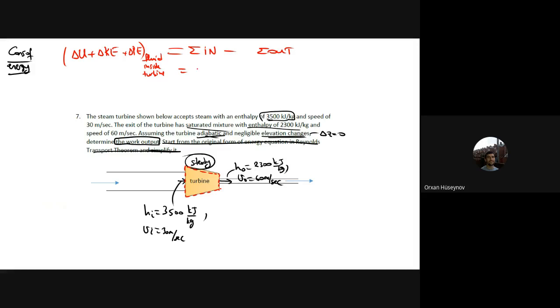And for the in quantities, you have the mass flow rate, so mass multiplied with the internal energy plus the P by rho plus the kinetic energy plus potential energy. This one is for inlet, and as well you will have the Q and the work. Minus, similarly, you will have the mass with the kinetic energy, potential energy, pressure, as well as the Q and the W. This one is for out.